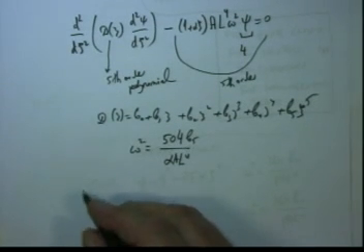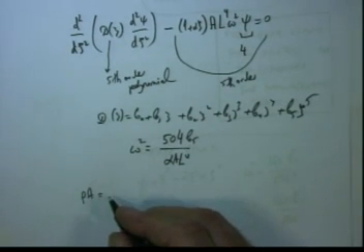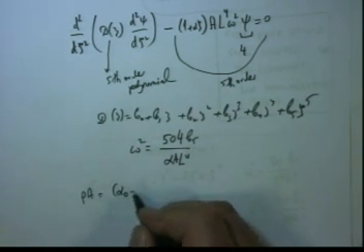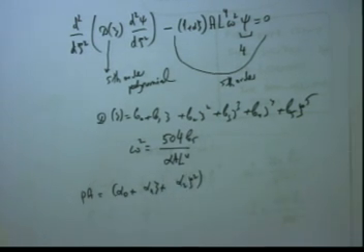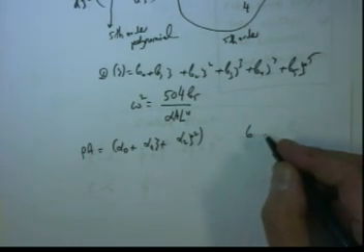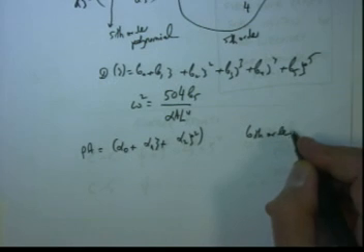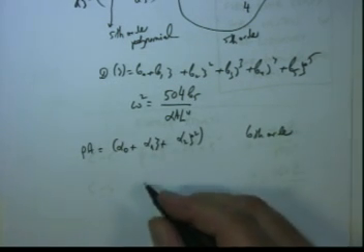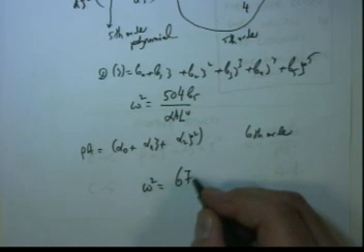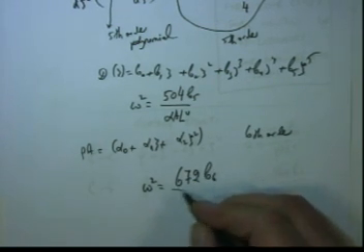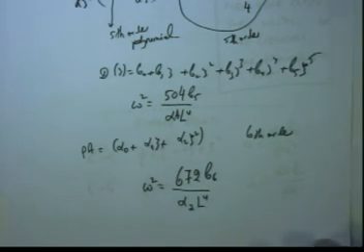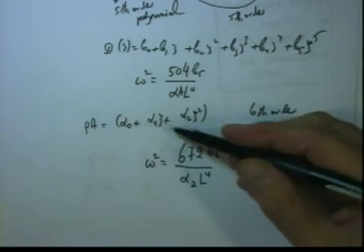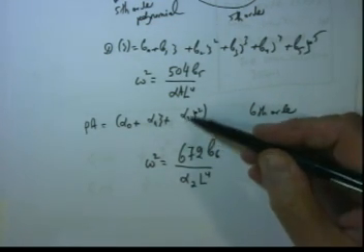Now imagine rho A equals alpha 0 plus alpha 1 psi plus alpha 2 psi squared. Imagine this one. Then we have 6th order polynomial. And the answer is for omega square equals 672 b6 divided by alpha 2 L in fourth power. Pay attention, it depends only on b6 and depends only upon alpha 2.